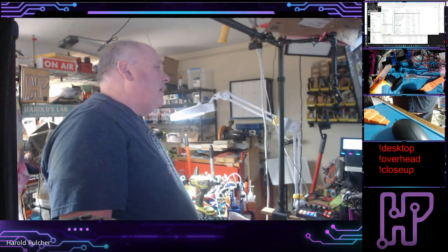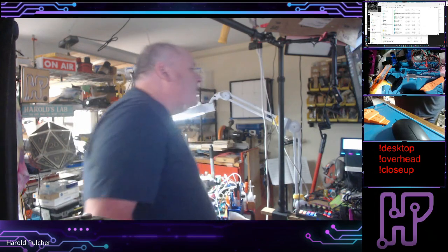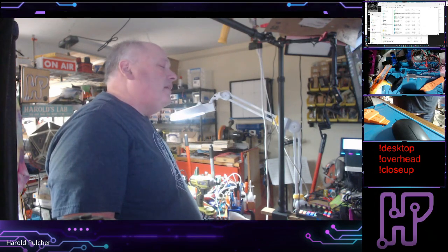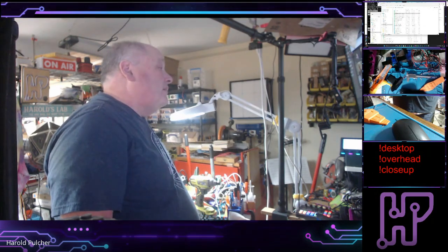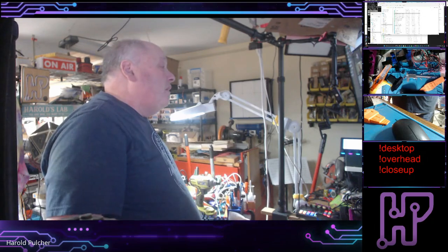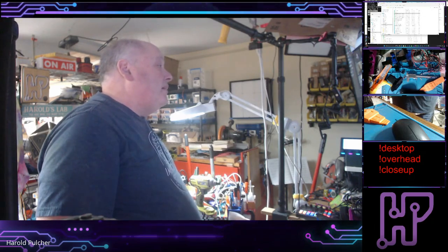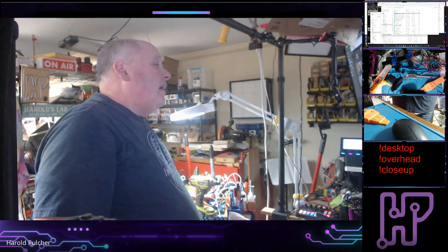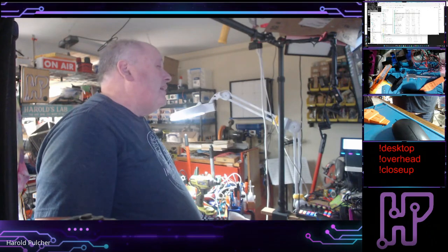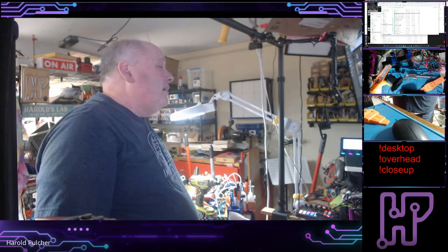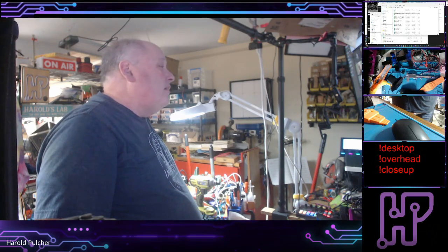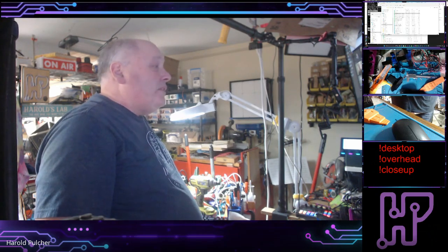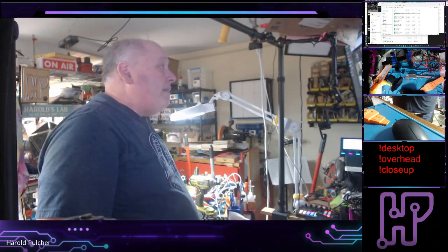I just glanced, Kyle, at your... I don't know, I jumped in late to this conversation. I don't know what kind of scope you have over there, but it's a Rigol DHO 804. I'd be very surprised if that thing doesn't have some kind of capability there to decode I2C and SPI, if that's what you're looking to do.